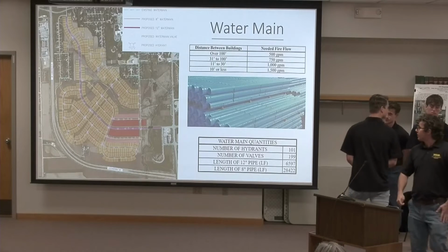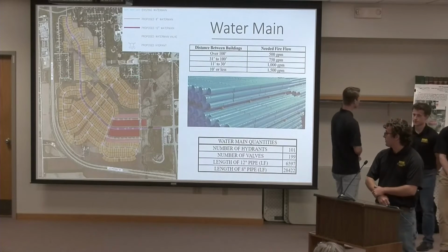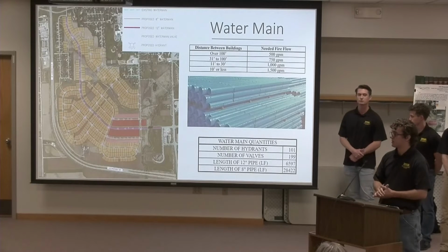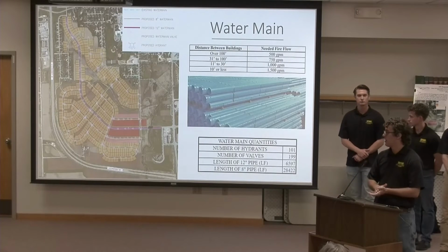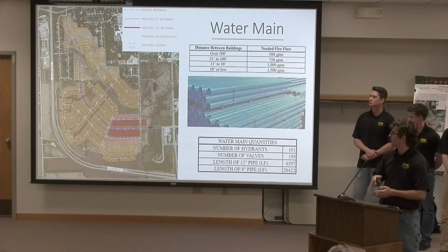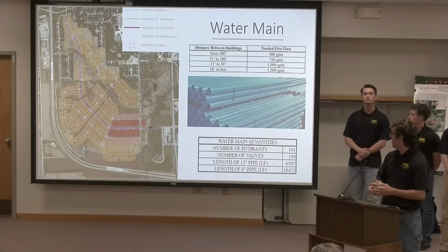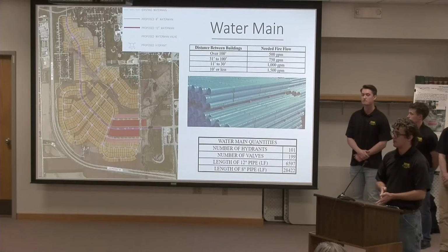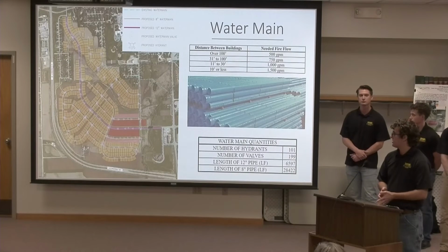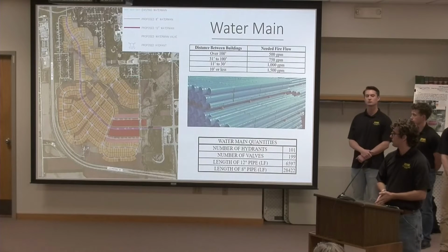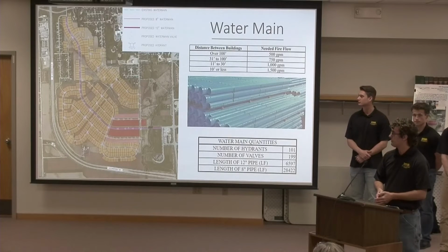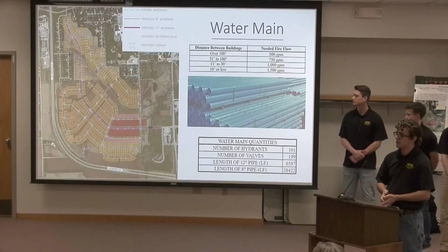In terms of the water main, it should be located either on the southeast or southwest side of the road, 1 foot inward from the back of curb, so it will be slightly underneath the road, with the arterial main running along the arterial road. In terms of hydrants, there should be one placed at each intersection, within about 25 feet. And then they should also be spaced in the single-family areas 400 feet apart, and in the commercial and multifamily areas about 300 feet apart. And they should be placed at high points whenever possible.